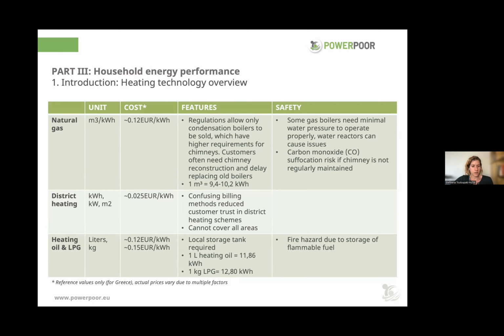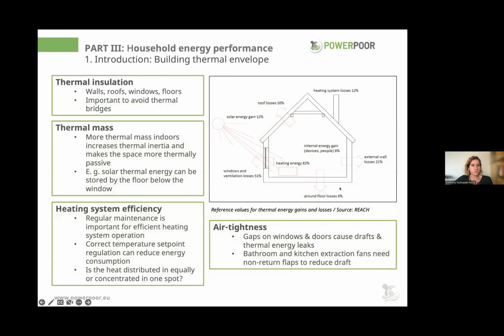And finally, for heating oil and LPG, a local storage tank is required, and this may pose some risks, again some dangers, because this is a flammable liquid. 1 liter of heating oil generates about 11.86 kilowatt hours, whereas 1 liter of LPG generates 12.80 kilowatt hours. And of course, there is the fire hazard that I mentioned before.